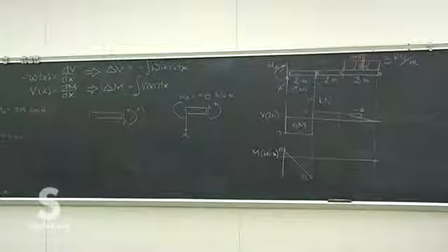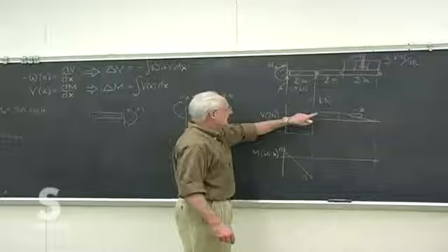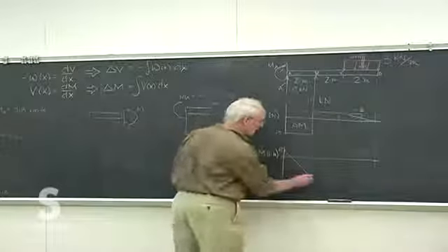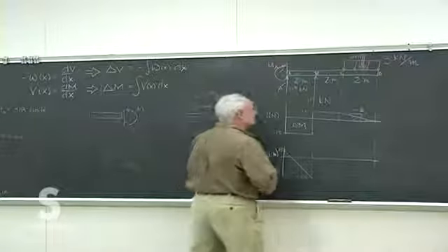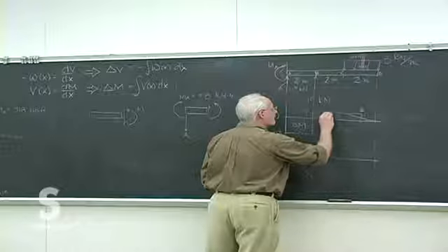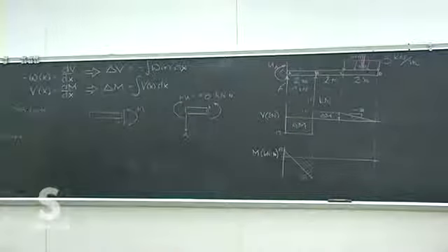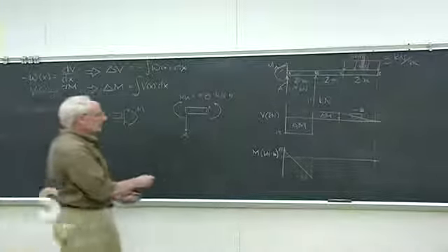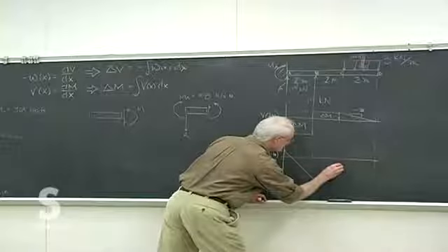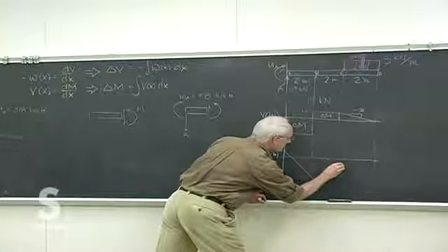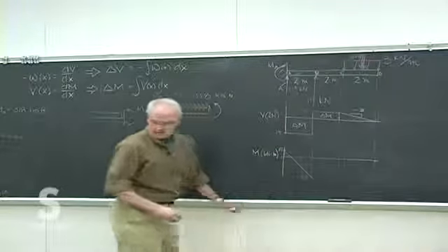No. Look at the shear diagram. It's positive. So the shear diagram then turns positive and constant. So we have a positive and constant slope. And we can figure out the delta M for that space. That's just a 12, so it goes up to, what, a -6? Which would put it right about there, I think.